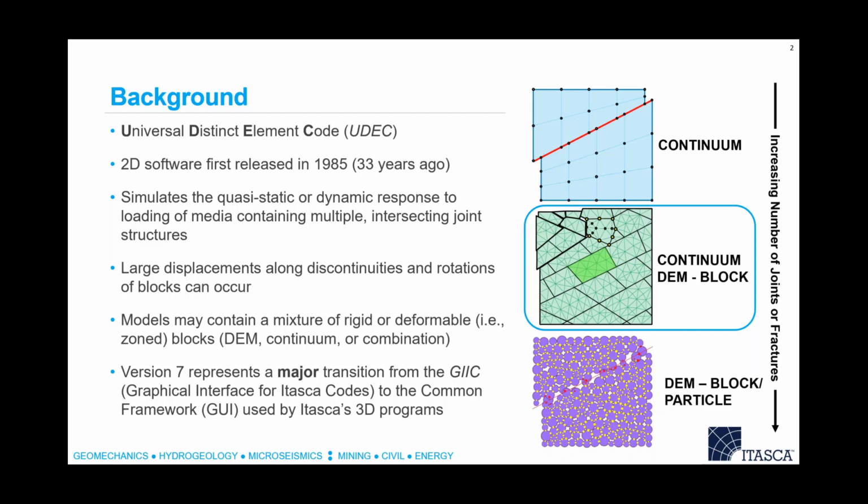And then you can compare that to PFC, which is our particle flow code, essentially a distinct element method and now block particle approach, where everything is based on contact interfaces. Your selection between the three largely depends on the increasing number of joints or fractures that you want to consider in your model.